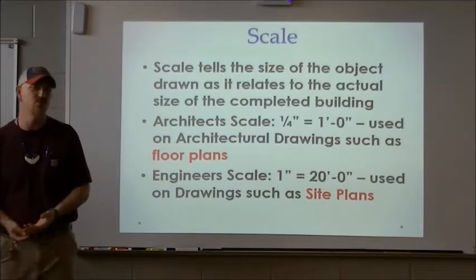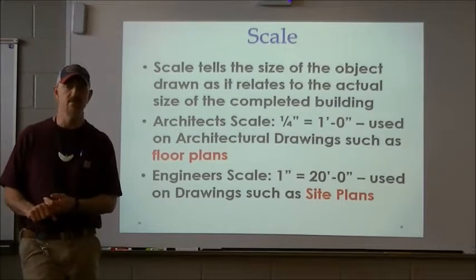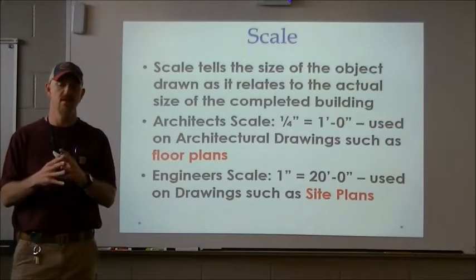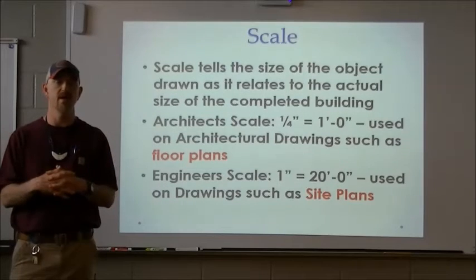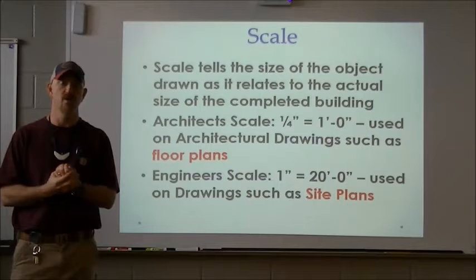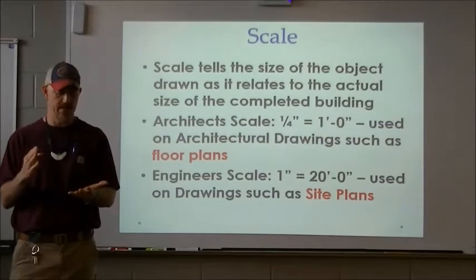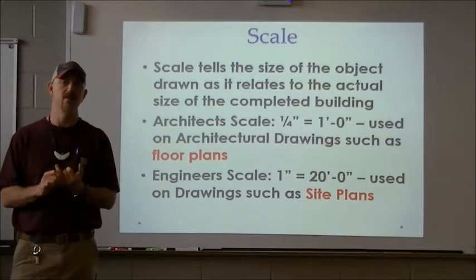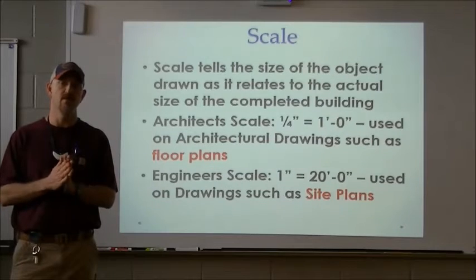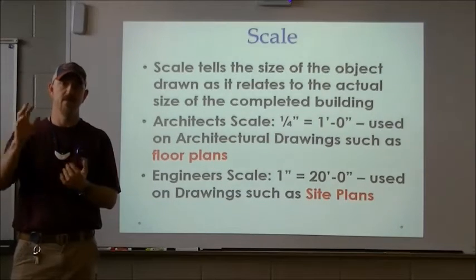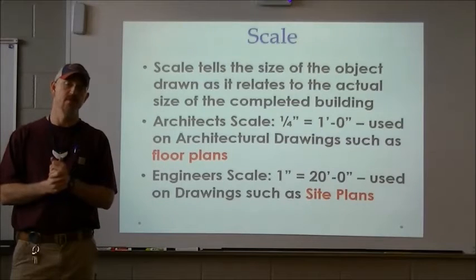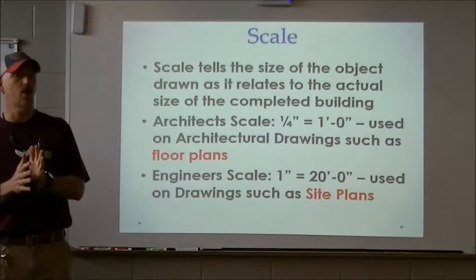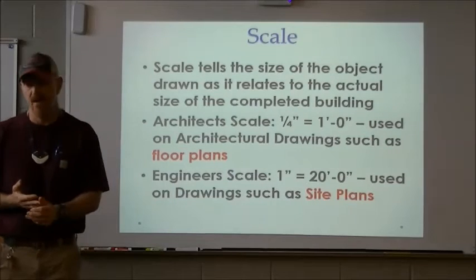Architect scale is usually 1/4 inch per foot for floor plans, and the scale can become bigger the more detail is drawn. So if we're using 1 inch equals a foot, obviously that's going to give us a lot more detail than something like 1/4 inch per foot.